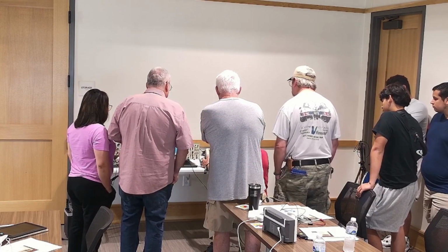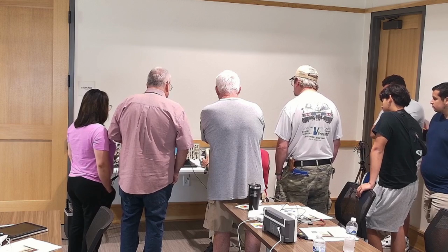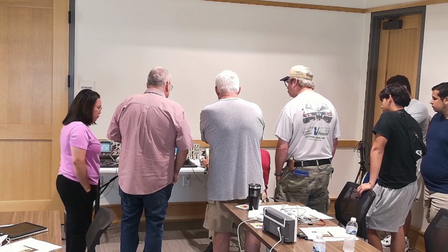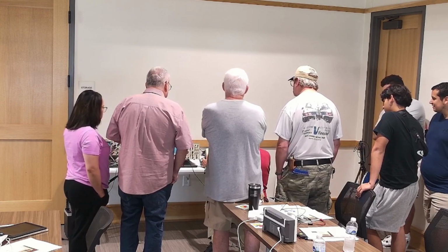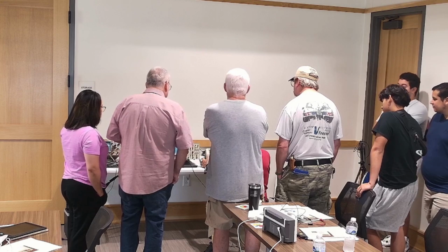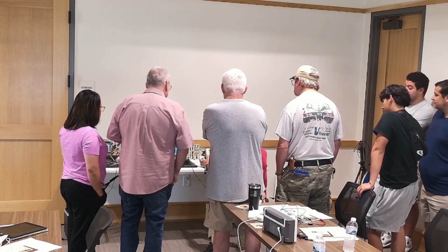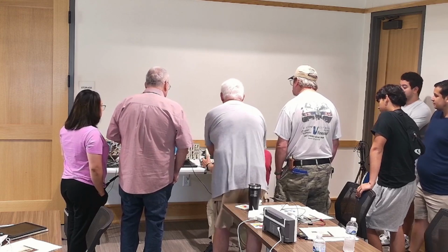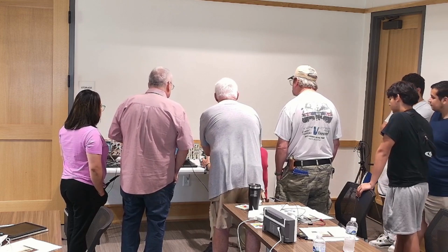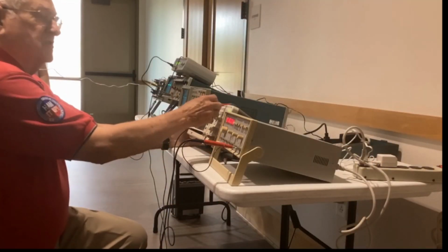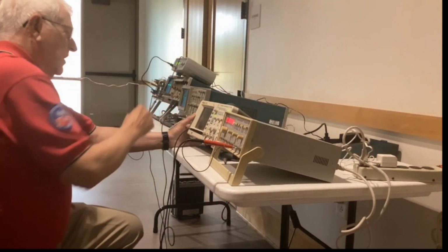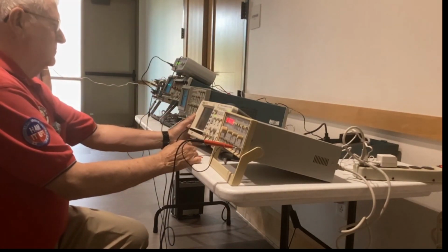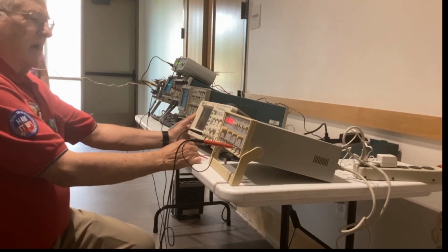So what's the frequency, somebody? 1 divided by 0.00025. This scope cheats. It's actually 199.954 kilohertz. This actually measures it for you. Obviously, this is a much newer instrument than these old guys over here. But that's kind of the idea behind that.